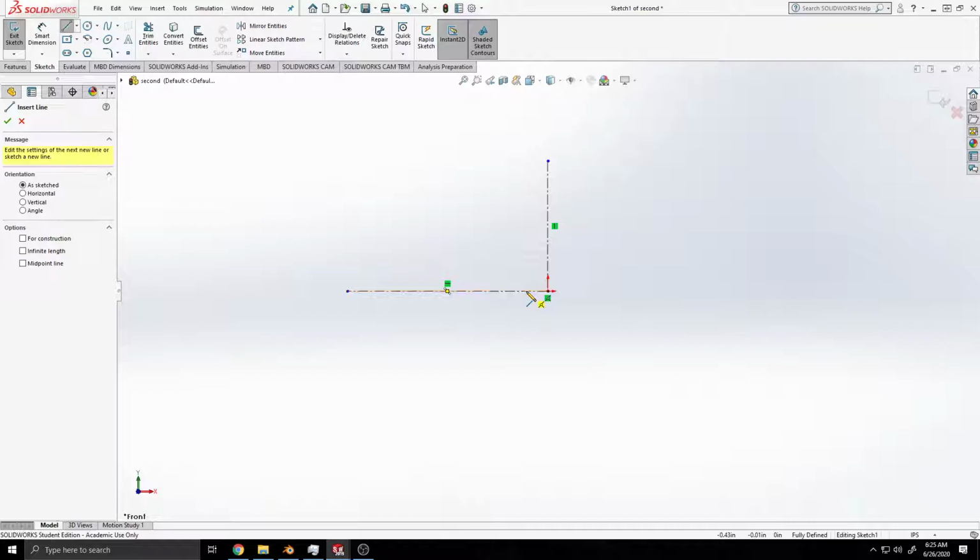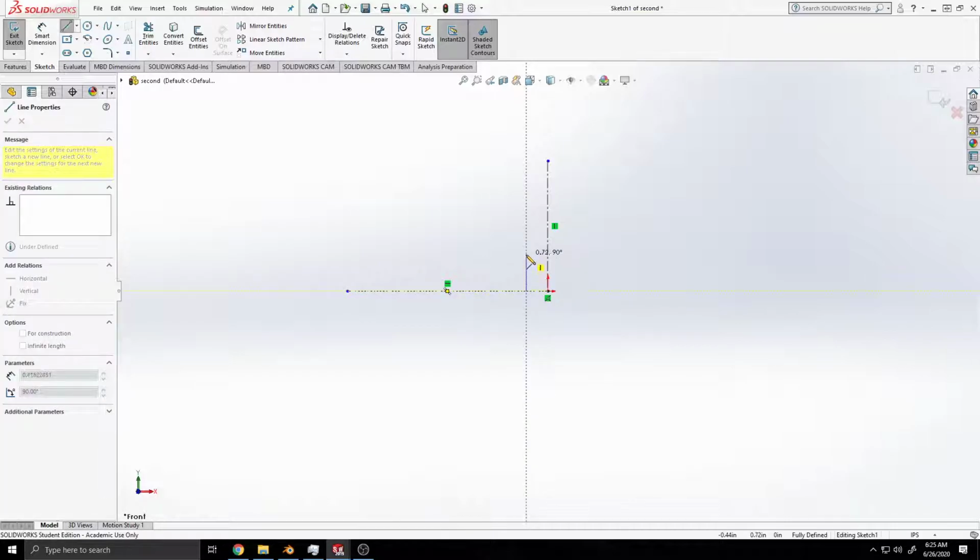Click. Drag up a vertical line approximately an inch. So like 0.94 I'm reading right now, and I'm at 90 degrees. That's good. Click. Drag across a very short little line horizontal. And you want it less than a 1/2 inch. So like 0.3, 0.4 is very good. Click. Drag down at a slight angle. Again, look at what I'm drawing.